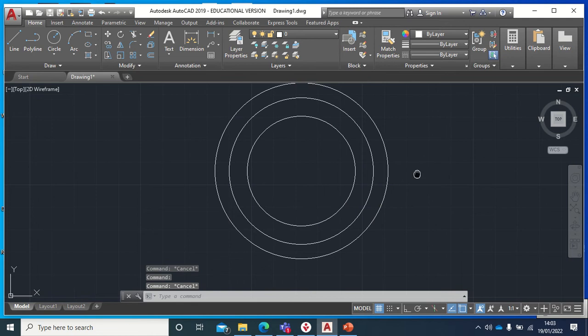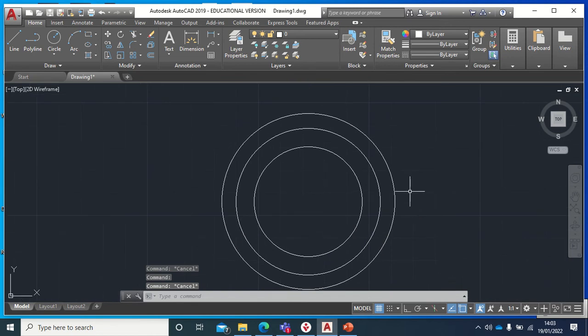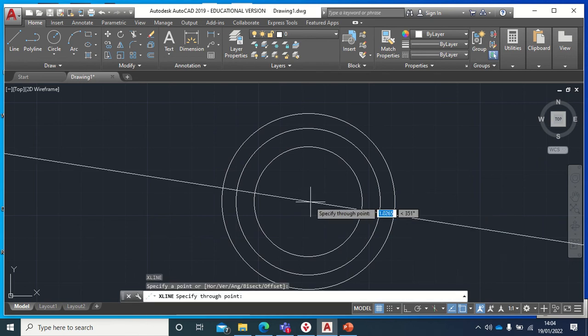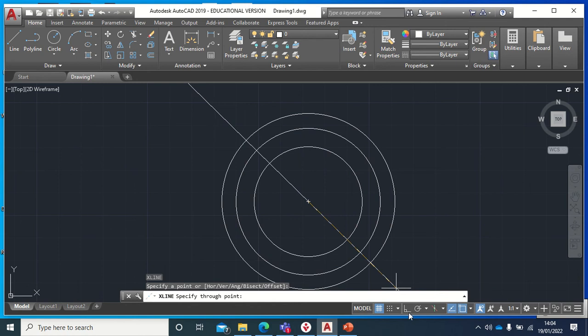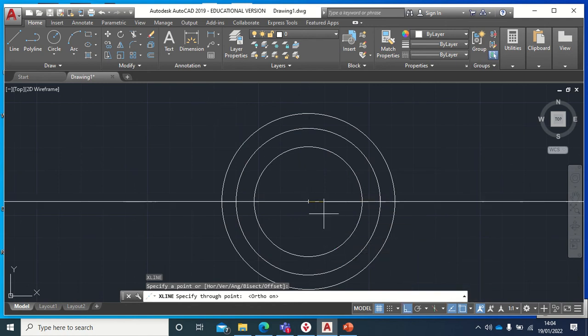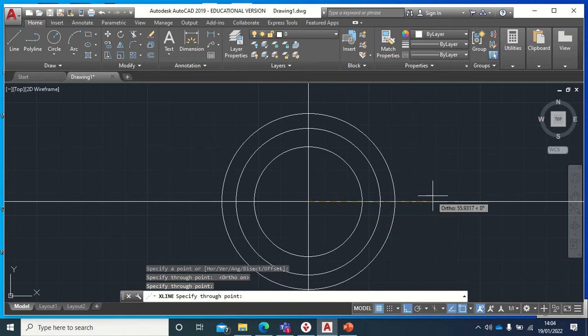So now you got this one. Now let's do this. Let's type. Do you know how to get the X line? The X line. So type X line and pick the X line. So just type X line and pick the X line so that we can draw. And please get the auto on. Let's draw a horizontal line here and a vertical one, and just exit for now.